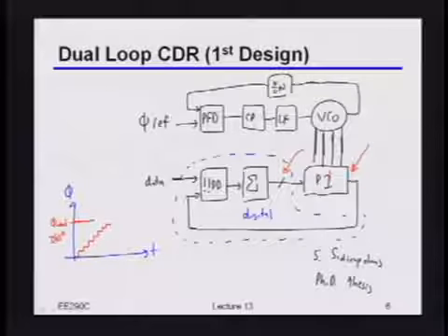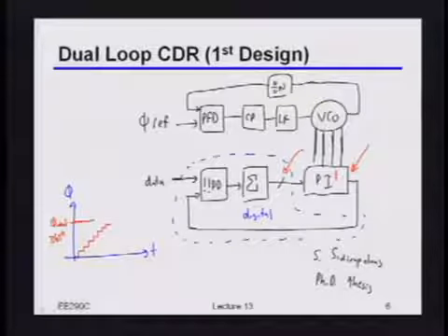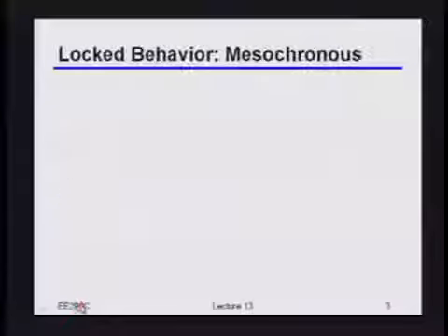So that always implies, of course, that if there's a finite resolution with which I control that phase interpolator, you can never get exactly the right value for the phase, right? All you can do is get close to that value and then jump around in that vicinity, right? So kind of what I'm implying here is that, and as an example, let's just think about a